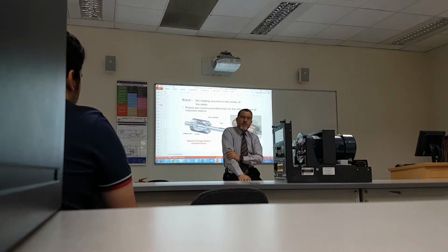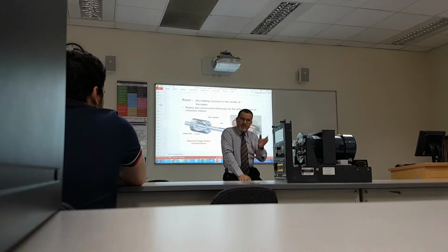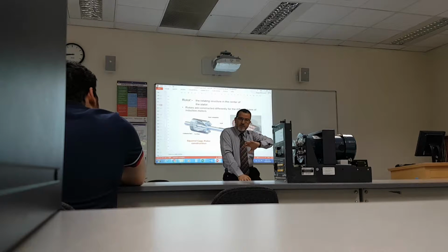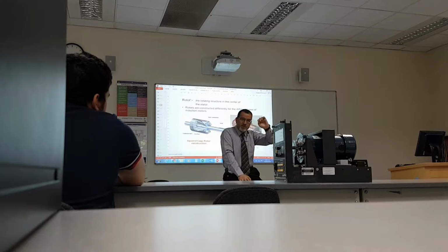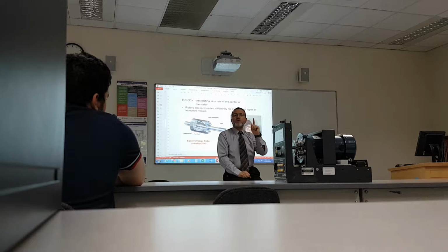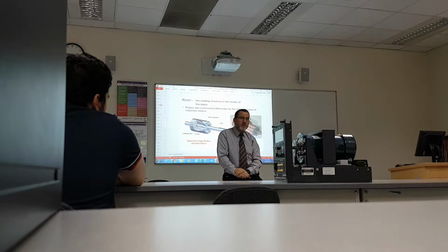Because you see, when you increase the load on the rotor, that means more current is flowing in the rotor. That means more current is flowing in the stator. Now, of course, it has a maximum rating. Remember that nameplate that we looked at before? That nameplate tells you the full load amperage. So if you keep increasing the load beyond the rated full load current, what's going to happen? It's going to heat up more than it's allowed to.